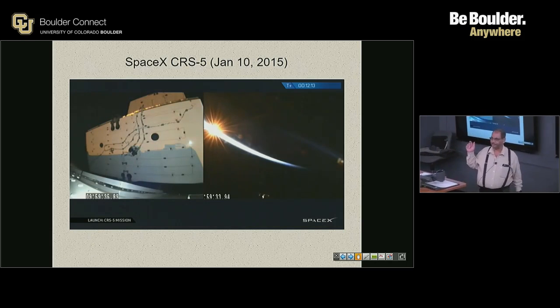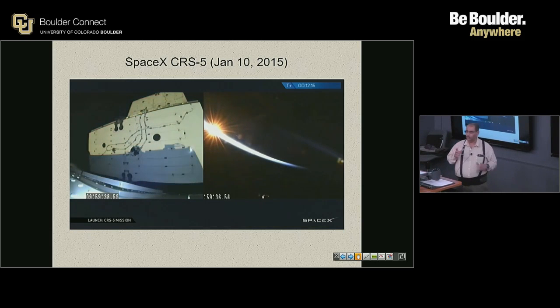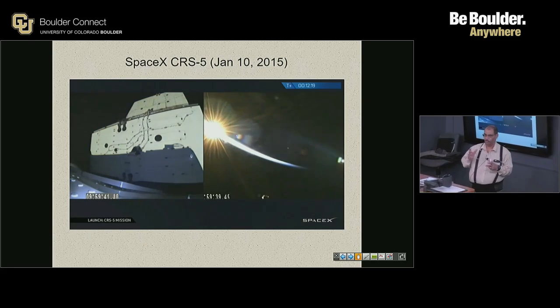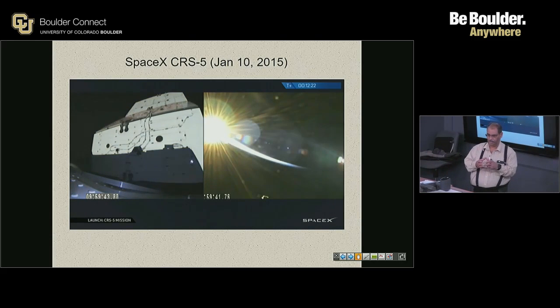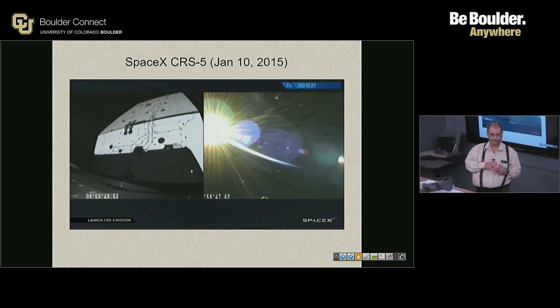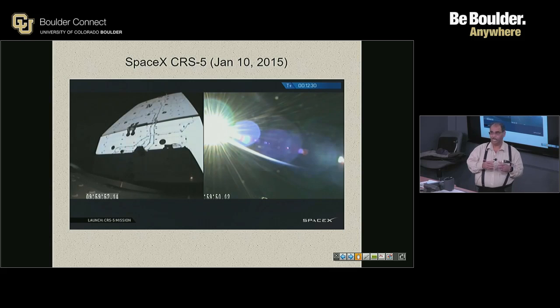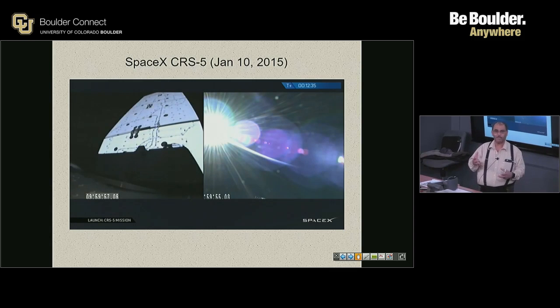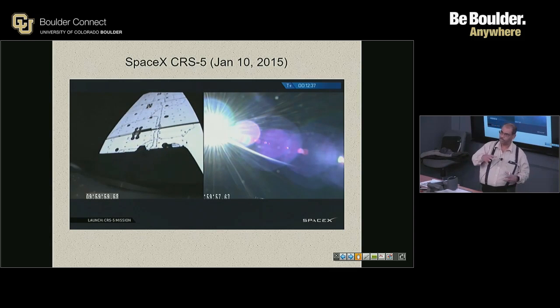The reason I'm showing you that is you have to make sure that the intake of the pump always has liquid propellant. So you have to have a certain G force acting. When the engine is thrusting, there's not a problem. The propellant is forced towards the outlet area. But when the engine stops thrusting in microgravity, you see that the propellant essentially becomes huge droplets.